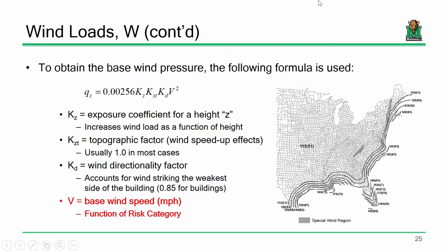Under seismic, that's a different story, because with seismic you can generate massive accelerations. But we're starting to go down the rabbit hole in the geotech aspects. In those instances, you're probably just going to have to use deeper piles, which generate a larger amount of skin friction to keep the building in place.